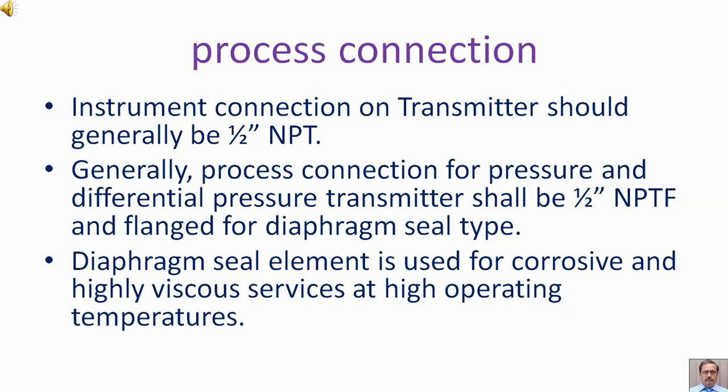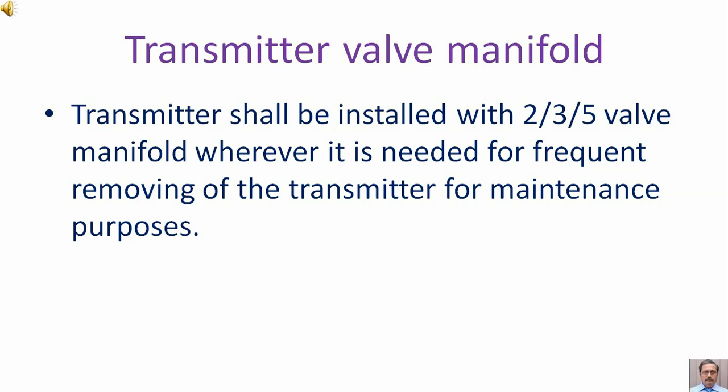Diaphragm seal element is used for corrosive and highly viscous services at high operating temperatures. Transmitter valve manifold. Transmitter shall be installed with 2/3/5 valve manifold wherever it is needed for frequent removing of the transmitter for maintenance purposes.